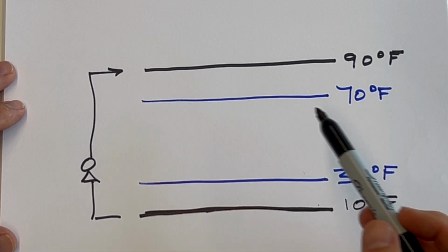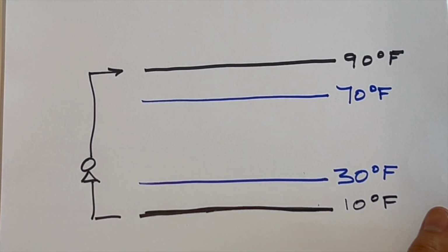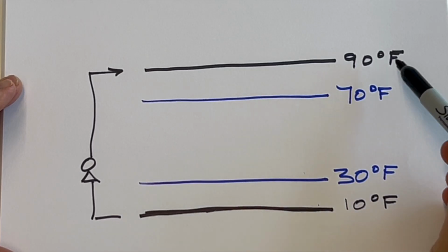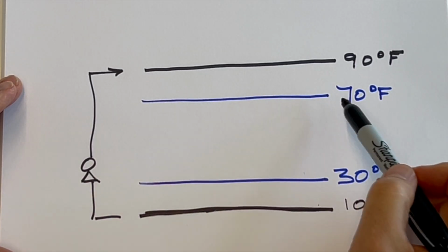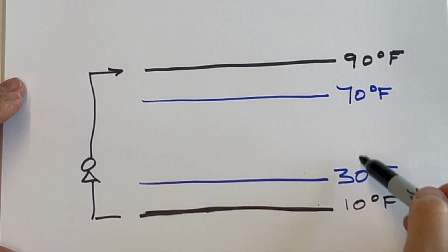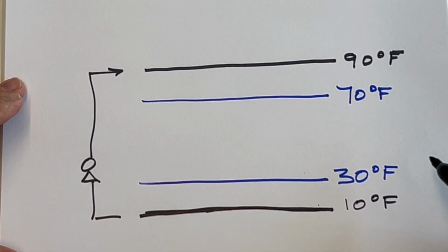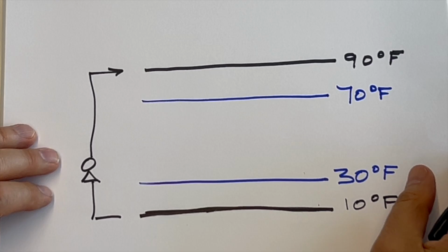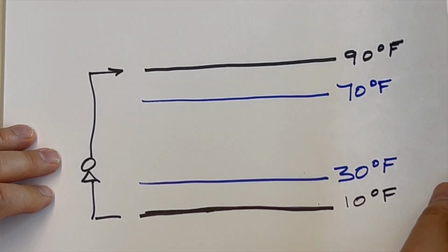And so the benefit of a variable speed heat pump, as seen through the temperatures of the air, the source, and the higher temperature, the indoor temperature, as well as the refrigerant temperatures: for the same indoor and outdoor temperatures, we can slow the compressor down. It needs to pump less. It uses less energy.